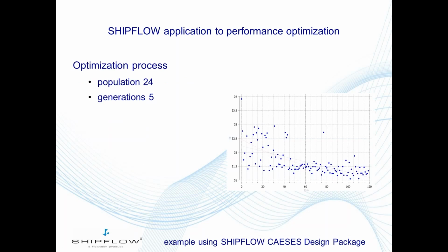And then the optimization is being run, and this example was run for 5 generations, with each generation consisting of 24 populations. So this means that you can send off 24 computations at the same time onto Rescale's cluster. And then you wait for results, and the next generation will be sent off automatically. So this will be like running 5 computations in series time-wise. So time-wise, it's really efficient to run this on Rescale's cluster.